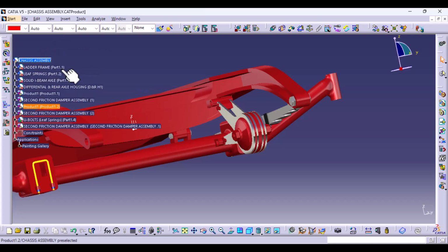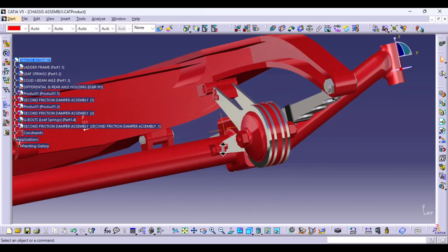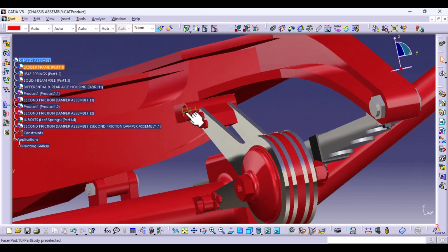I think we are going to create a new part so that we can then assemble them. So we are saying one of the bolts is 40 plus 10 plus 10, that is 60. We've got a 60 length here plus an extra, maybe an extra 10. So that's about 70 the bolt length. And we've got a hole of 15 millimeter diameter.